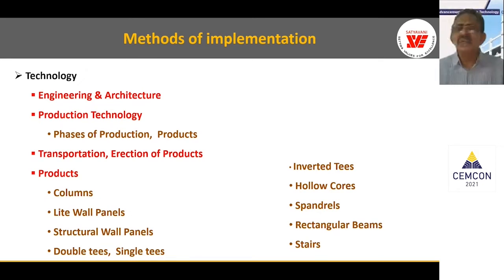We know it is very difficult to handle the accuracy of the tread and rise that is designed. With the precast, we can straight away go for adhesive and the tiles or the stone fixing very easily and maintain the accurate tread and rise dimensions in the precast stairs.